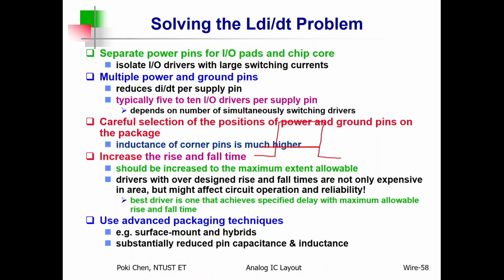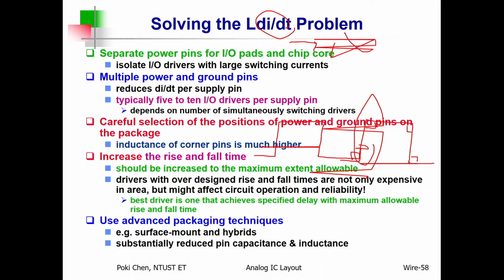Oh, perfect, right? You have 90 degrees for the turns. 90 degrees here, 90 degrees, 90 degrees. It looks beautiful, but in performance, it is so ugly, because for such a very fast change, the dI/dt reaches infinite.